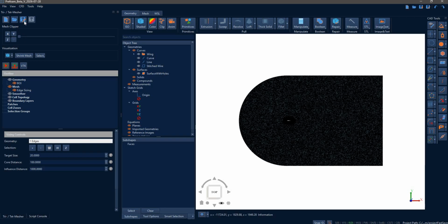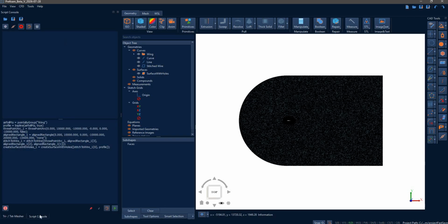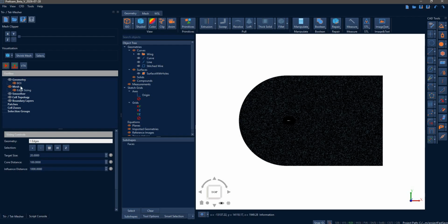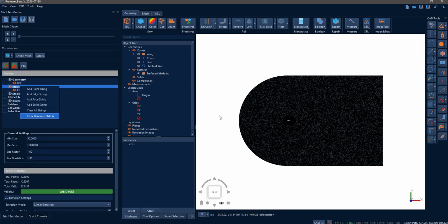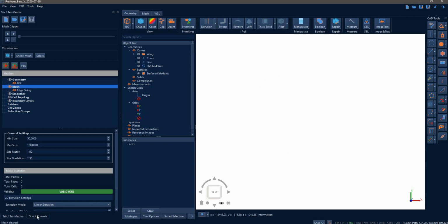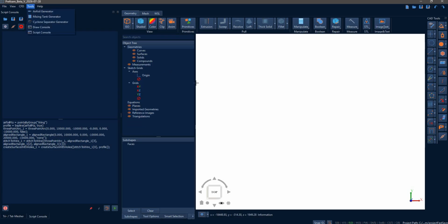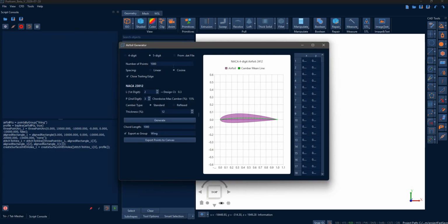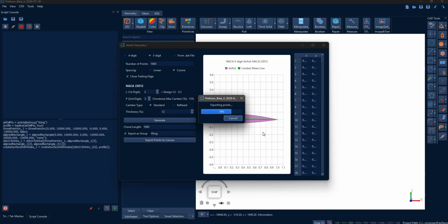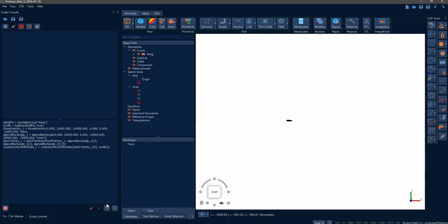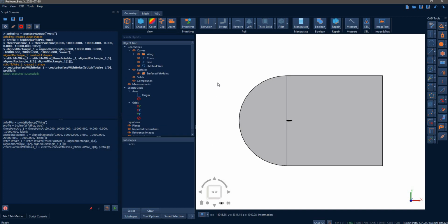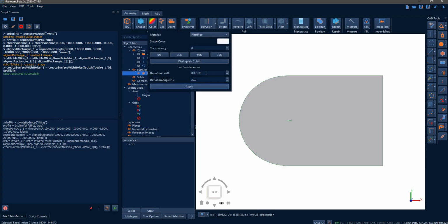The thing is, what I want to show now is, let us erase the created mesh, clear generated mesh. So I will show you another thing, remove all, and let me basically create another airfoil. And then I will replay the script. And once I have the fluid domain, let me crank up the resolution.